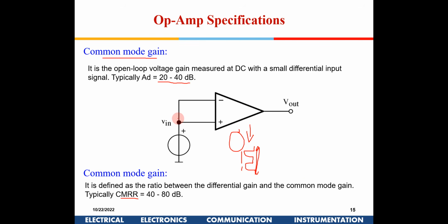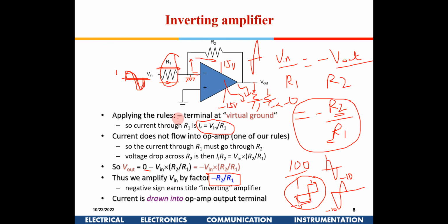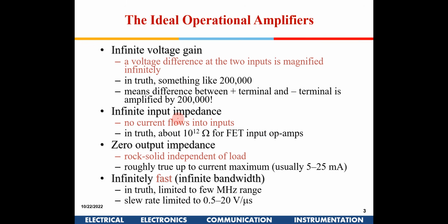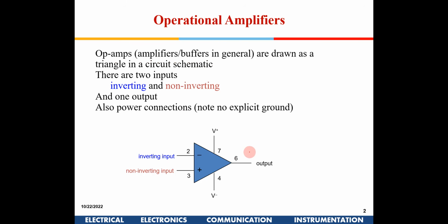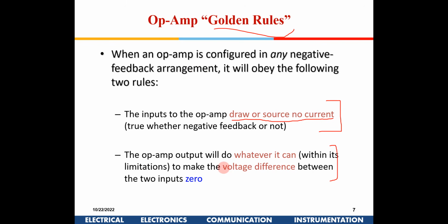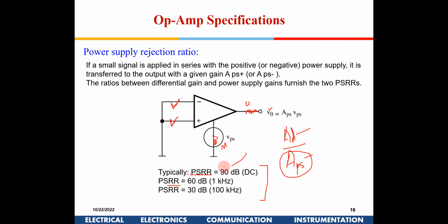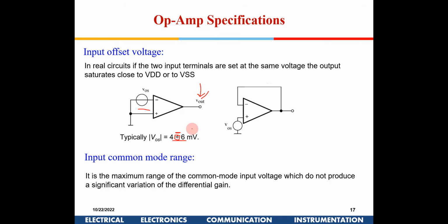Now when I talked about the 741 IC, there are some pins, Syed wanted to know what pins 5 and 1 are. We can use a small potentiometer between those terminals and adjust this output voltage to 0. Internally, the 741 allows us to give some offset voltage so that this output is 0. Is it okay with all of you? What is input offset voltage? Yes, sir.